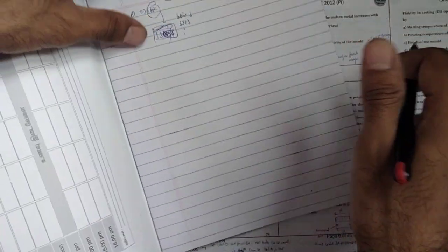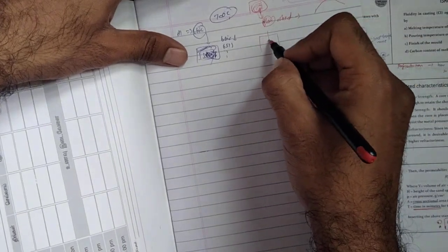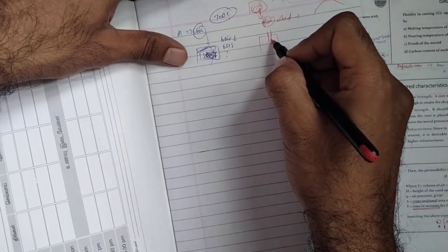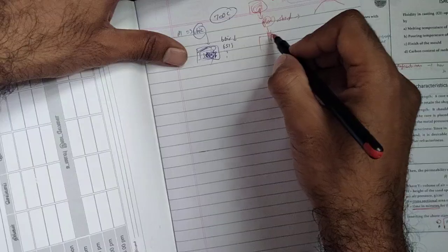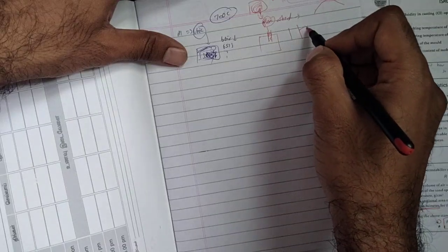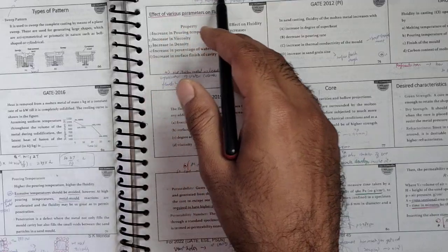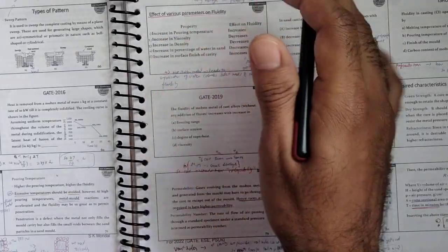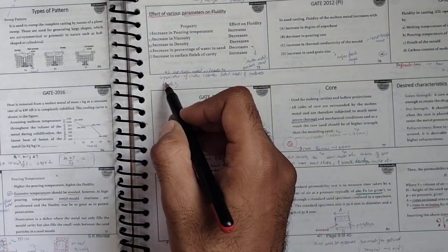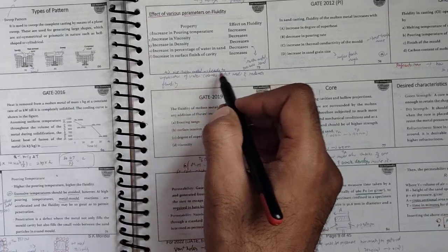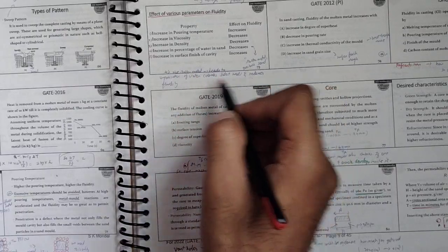For example, with the molding property, if the surface is rough, the fluidity doesn't go so far, but if the flow is smooth, the fluidity goes further. A smooth cavity means fluidity goes well, and a damaged cavity gives less fluidity. Also, a hot metal mold leads to evaporation of water, which absorbs latent heat and reduces fluidity.